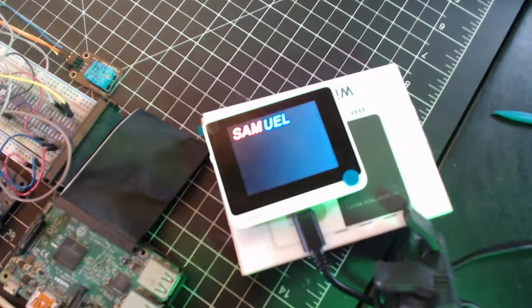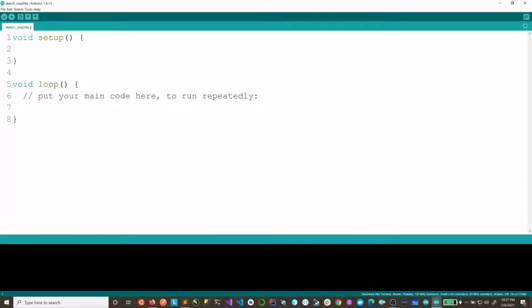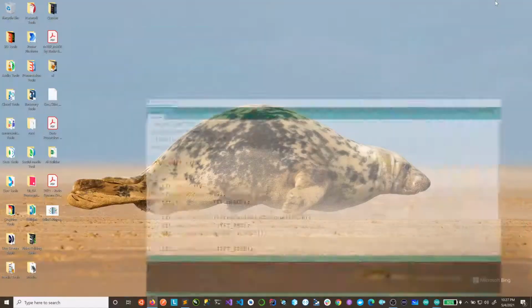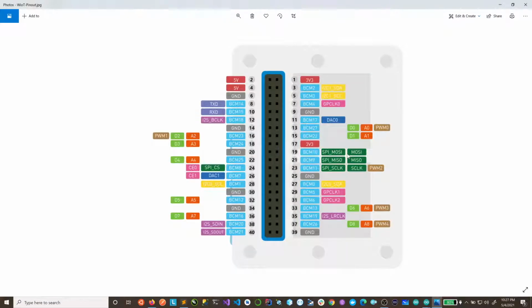In the setup for your terminal to use any analog devices, especially for the Grove connector, obviously you need to set the pin mode, and like I mentioned, you can access the pins from the schematics from A0 all the way to A8. Let me show this so that it doesn't look like magic to you. I'm using that reference.